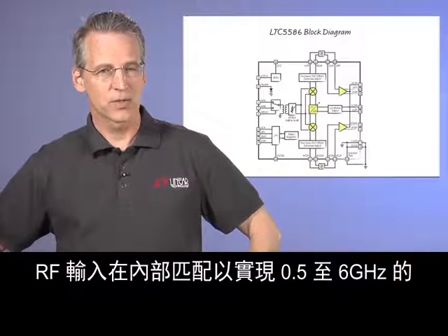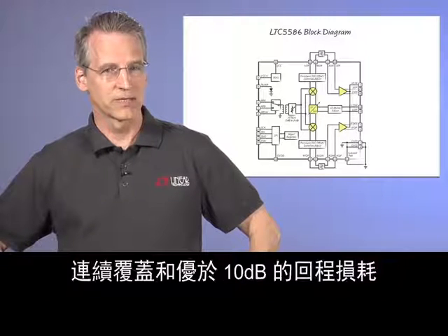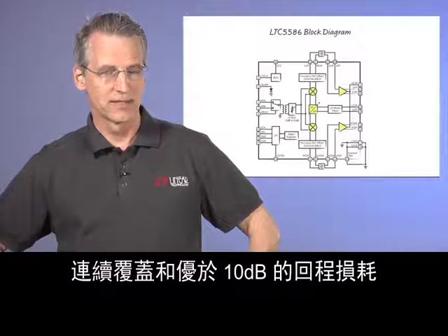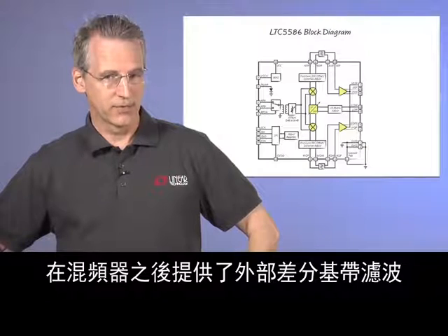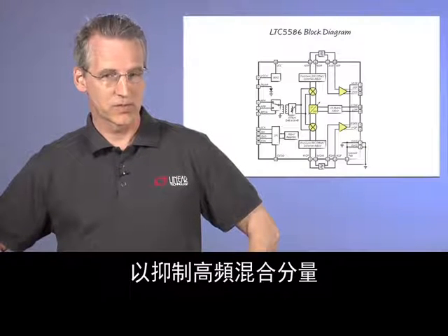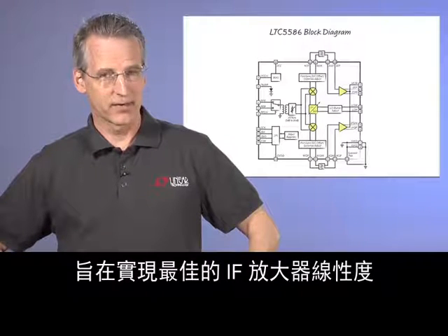The RF inputs are internally matched for 0.5 to 6 gigahertz continuous coverage with better than 10 dB return loss. There is provision for external differential baseband filtering after the mixers to suppress high-frequency mixing products in order to achieve best IF amplifier linearity.